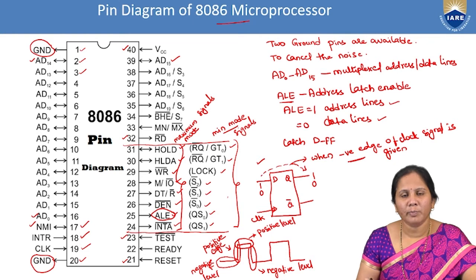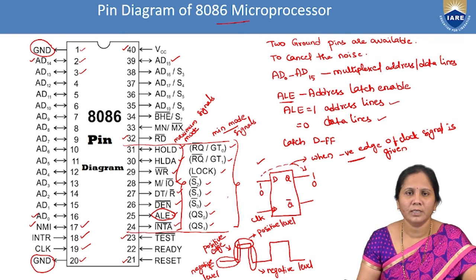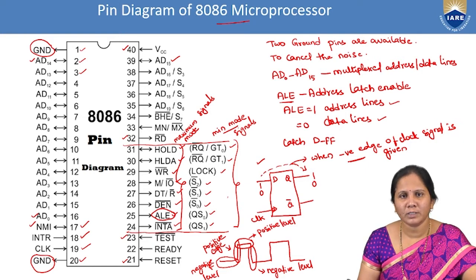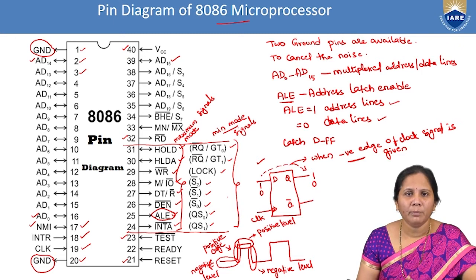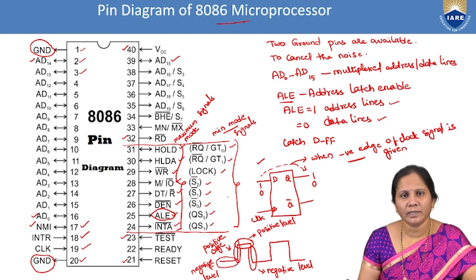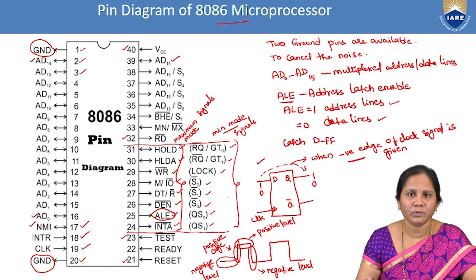The oscillator will be producing the frequency. There are a number of oscillators that can generate the frequency: Hartley oscillator, Colpitts oscillator, LC oscillator. But out of all those, we prefer the crystal oscillator to produce the frequency for 8086. Why? Because the crystal oscillator has high stability compared to the remaining oscillators. That is why the crystal oscillator is used for the 8086 microprocessor.